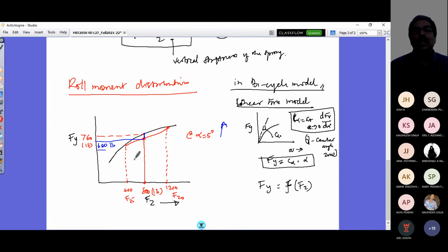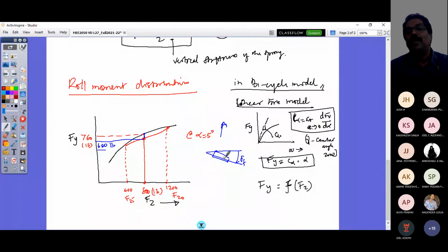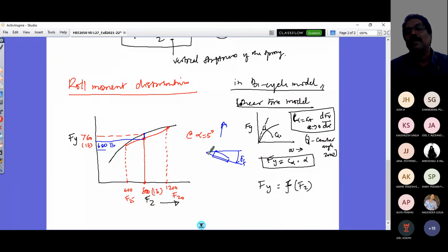So what is happening here is you understand the tire behavior. The slip angle increases. If this slip angle increase happens on the front axle tire, what will happen? You would have more Fy in the front axle and the front axle will plow out of your motion. So you are taking a turn to this side, but rather than doing it, your slip angle would always be like that. You know the bicycle model, you've seen it, right? If you are steering here, this is your delta F, and your slip angle is measured from here in this direction. Your slip angle is this alpha F.